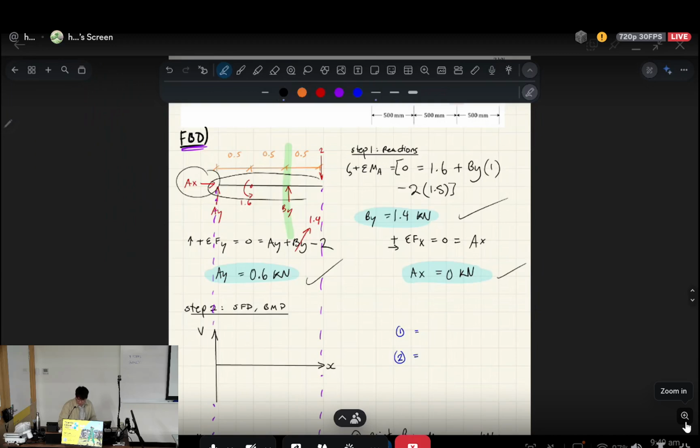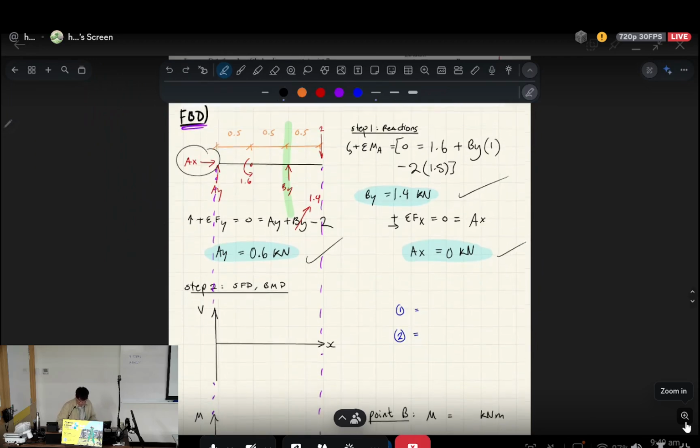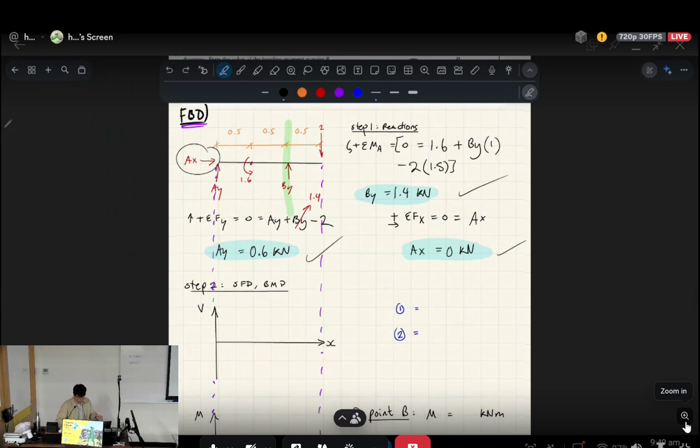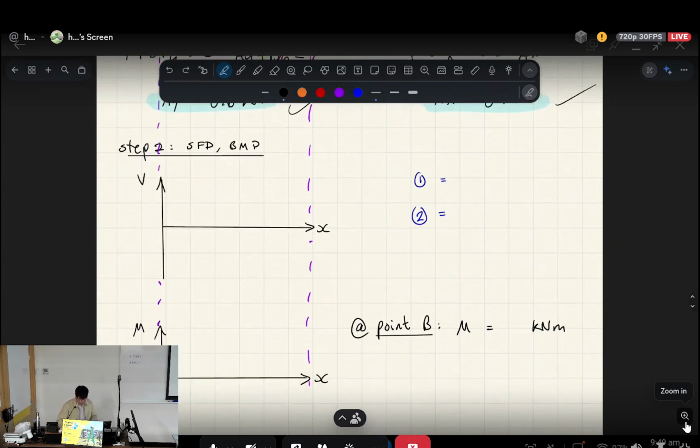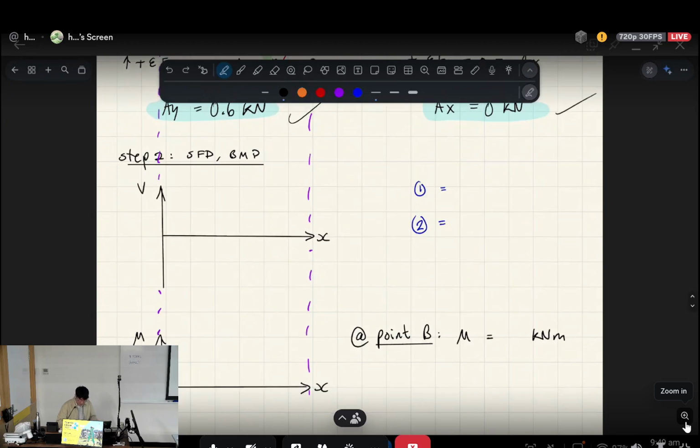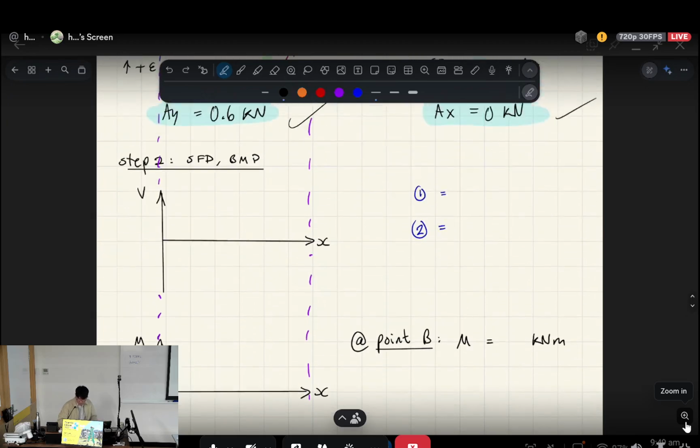So we know the beam is this long, okay? So however long I've drawn it, like so. The left should line up with the graph on the left, and the right should line up with the graph on the right when you're drawing the shear force and the internal moment, right? This is just a more clear way to explain shear force and bending moment diagrams. It's not a requirement, but I think it's a good habit.